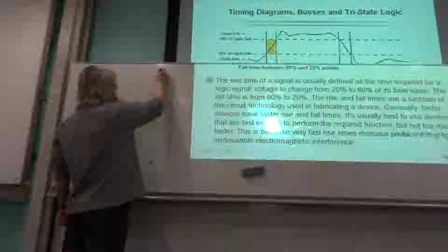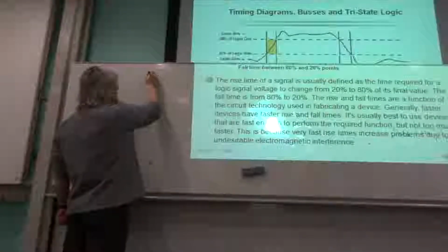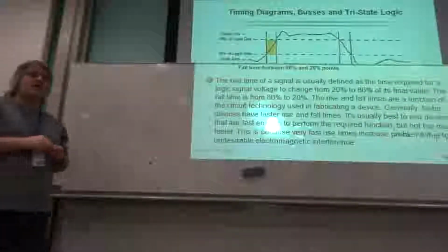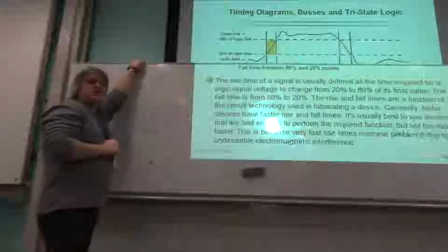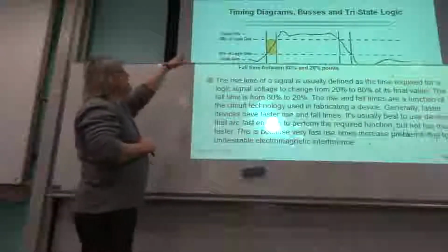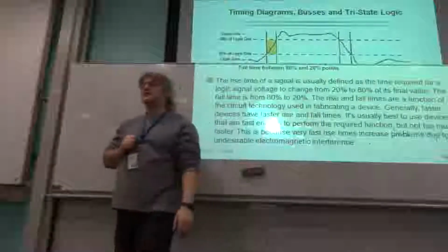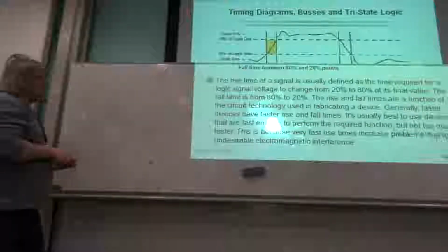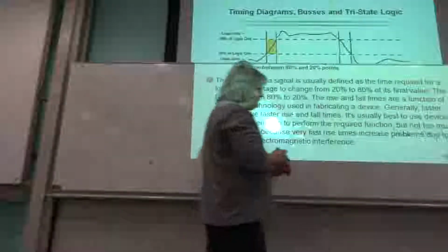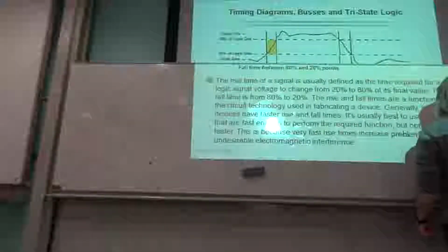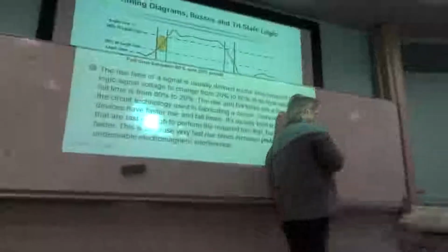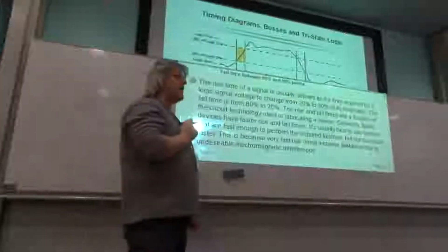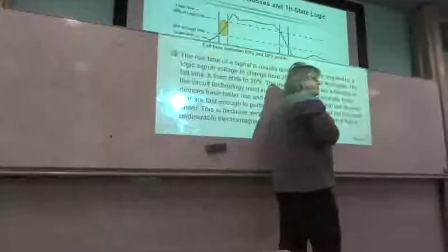If, for example, you're loading anything into latches, you're loading one value and then you're loading another value thereafter. There'll be a maximum speed at which you can do that, which is governed, to some extent, by the rise and fall time associated with that logic family. The rise and fall time, as I've mentioned, is typically family-based. So you might, for example, have CMOS technology, traditionally regarded as a relatively slow technology. The rise and fall times are quite long in traditional CMOS.